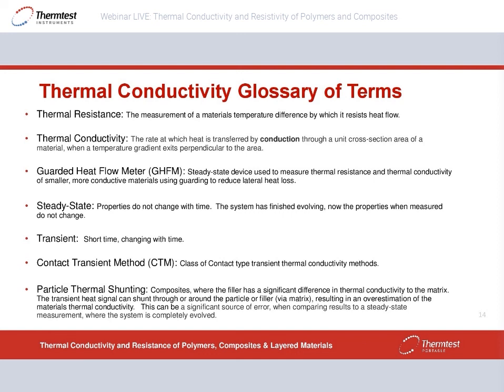It's the same question, the micron thick. So again, the ability to measure one single layer of a material at the micron level is not possible with this method. Again, there is a strategy to layer several pieces of thin materials to multiple defined thicknesses and measure the resistance of those, and you can get the relationship of conductivity minus the contact resistance. That's described in the standard.